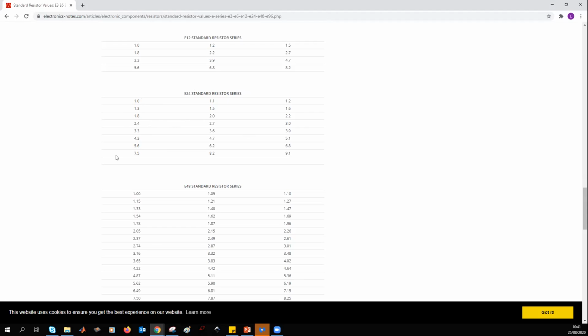You can see that the resistance that I calculated was 160. So here, as you can see, we have 1.6. So 1.6 means that we can find the 160 ohm in the E24. So the 160 I calculated is correct. We can keep it, okay? But if it was 165, for example, or I don't know, 31, then there is no 31 here in the table, so you have to change it, okay? In our case, I calculated 160. Here we have 1.6, which multiplied by 100 gives me 160. This means that 160 is inside the standard E24, okay?